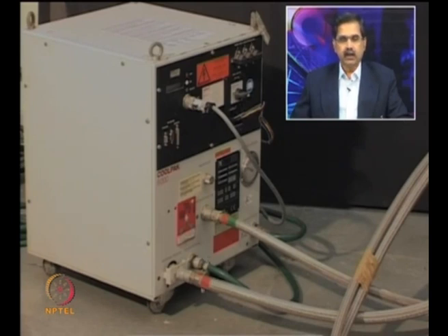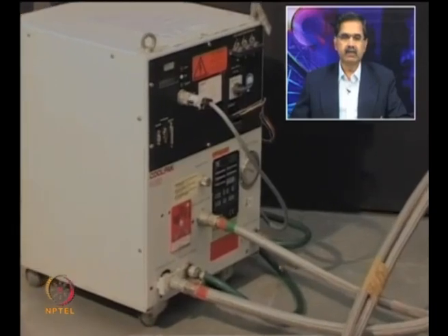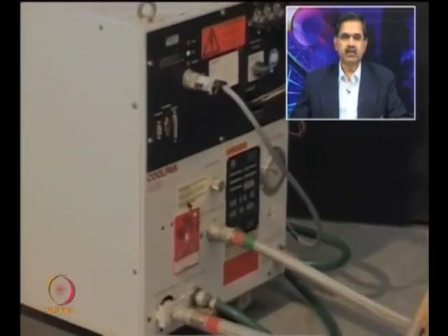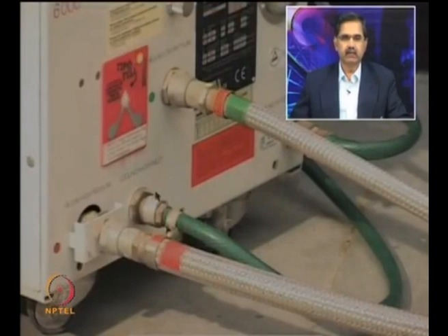This is a high pressure line, this is a low pressure line, this is where you can read the pressures, and this is the on and off switch of the compressor. As you will see further, the gas will get compressed from here, the gas will go from here to the cold head, and the low pressure gas will come back to the compressor, and there is a capsule inside and a water cooling arrangement.